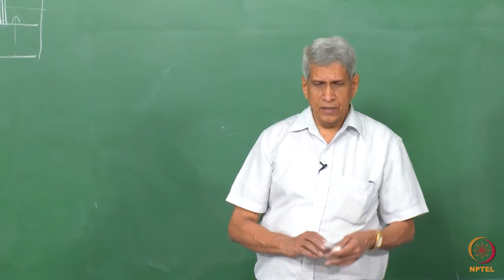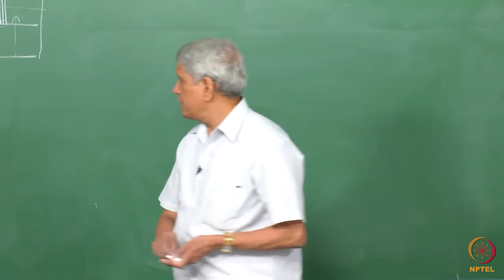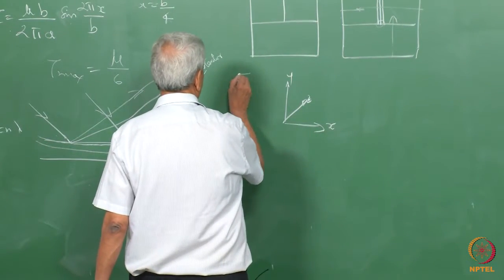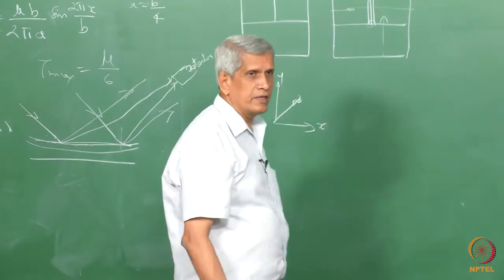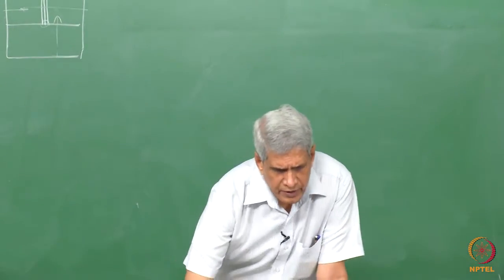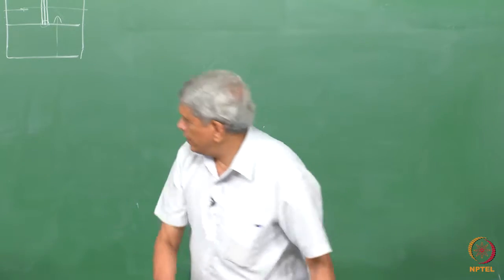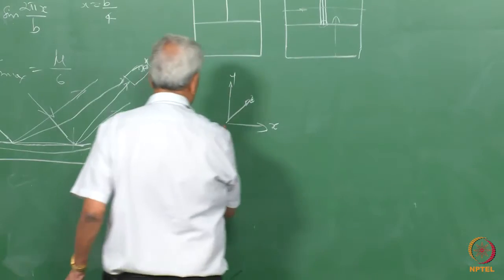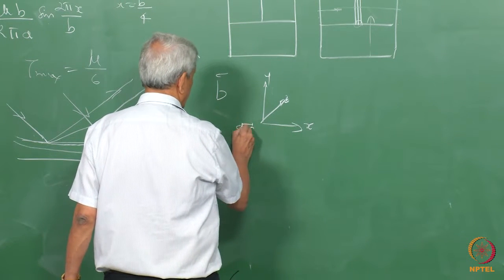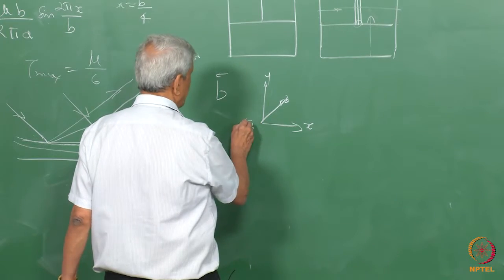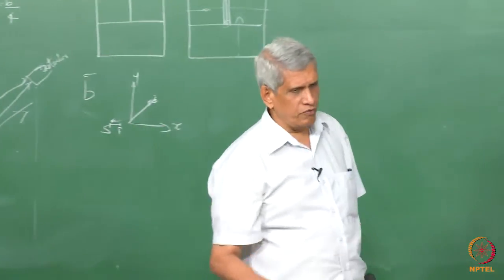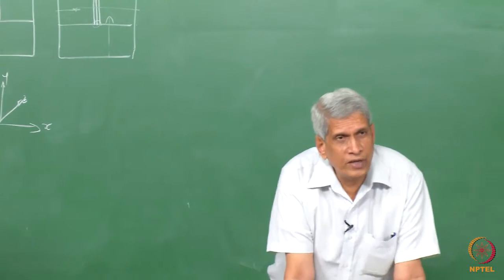This Burgers vector b is always a negative one, correct? Because with respect to the coordinate system which we have defined, this is the positive x direction, but the step is from finish to start, so this vector is in this direction. This is a convention which is used to find the Burgers vector.